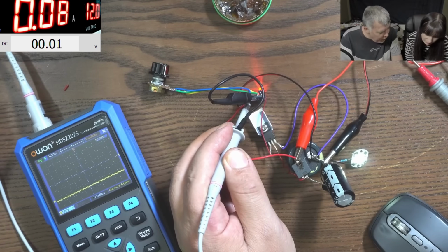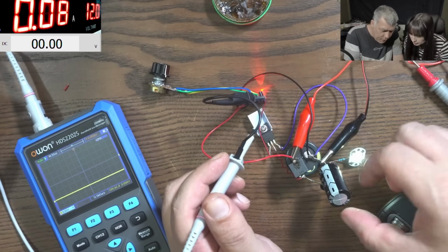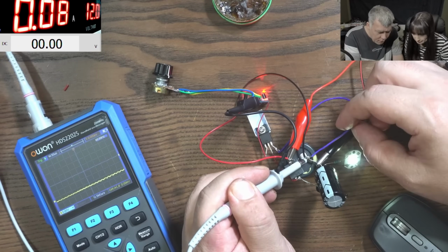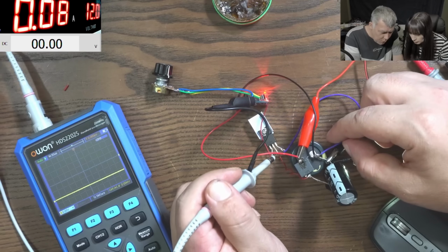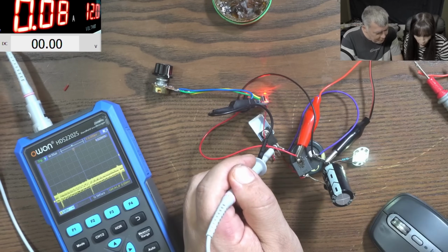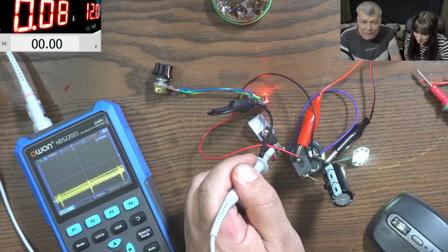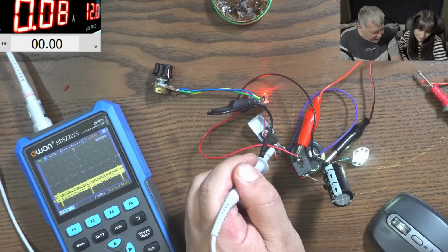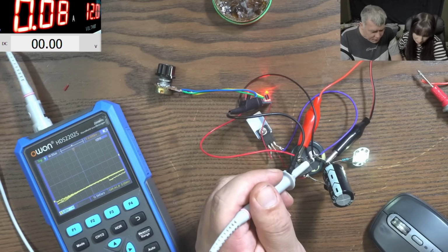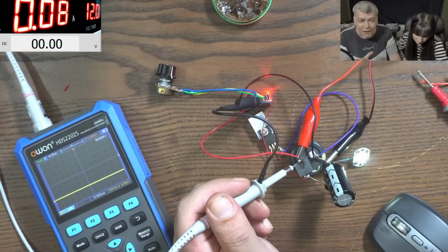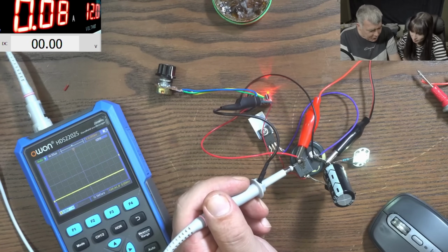You can see we don't have any spike. Do you understand? What will happen if I check here, and after this wire, which you said is just a wire? Check here, just to understand how much the signal is changing on a 10 centimeters wire. You understand how much a wire is affecting this circuit? So this is the switching here, and this is the switching after 10 centimeters of wire. You understand how critical it is not to have wires on a circuit like this?